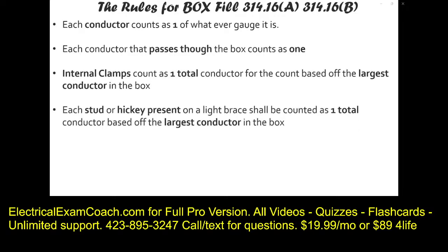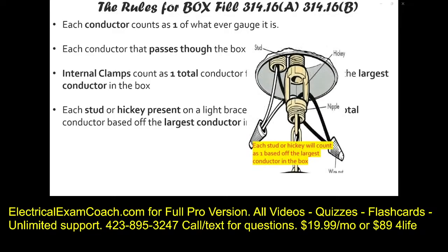Next, each stud or hickey that is present in the box shall count as 1 total based off the largest conductor that's in the box. Now, these are really old words, probably from the 30s if I had to imagine, but they still use them on examinations today. And this is what we're talking about.